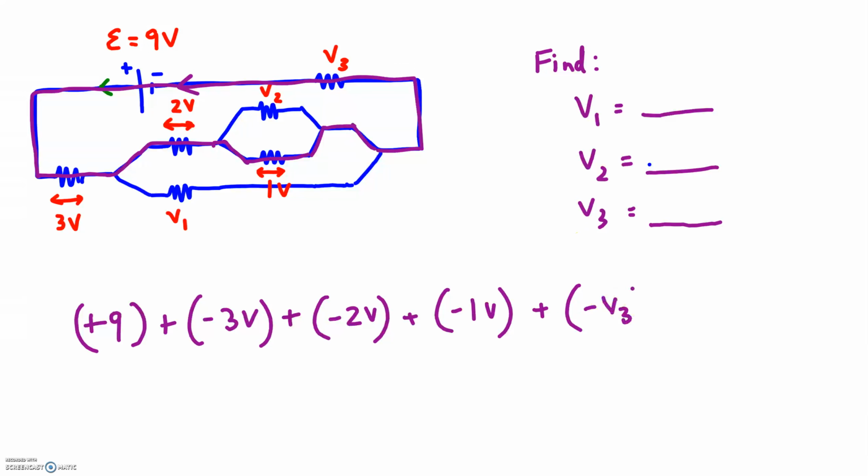That's a negative value because they're losing energy across that third, final resistor. Fourth resistor, I guess. So we solve for V3, right? This is in volts here. If you do 9 minus 3 minus 2 minus 1, that's 6 that we subtract, and you get 3 volts equals V3, like that. Okay, 3 volts.